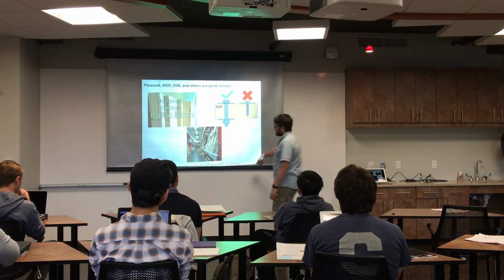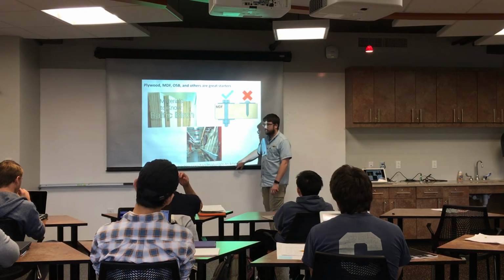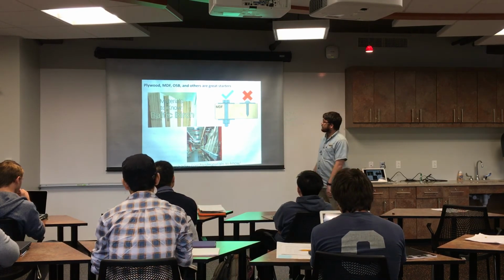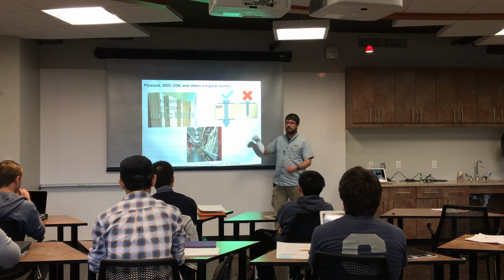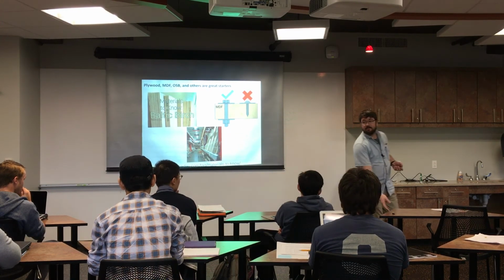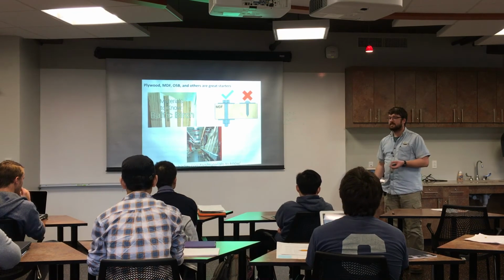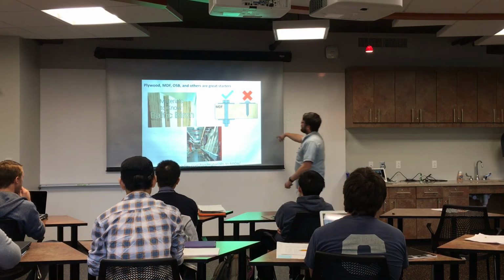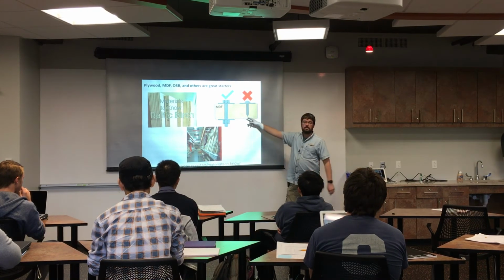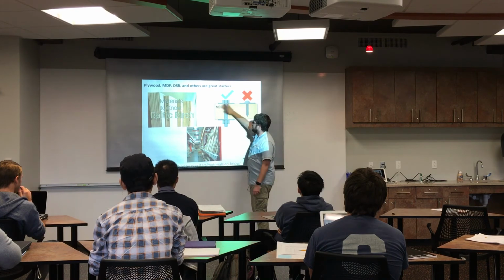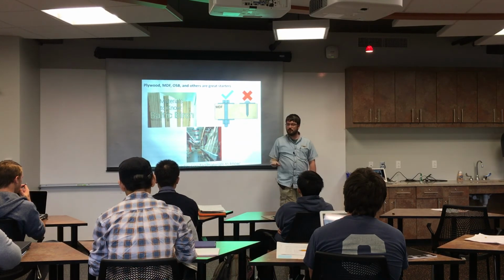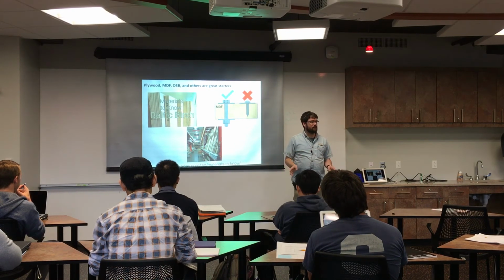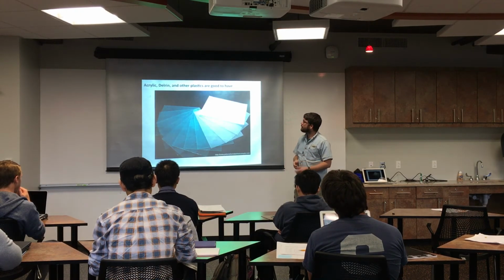There's this link in the slides, Hackaday, Materials to Know, that goes over a lot of materials like plywood, like MDF, and tells you things you should know. Like, for example, MDF, which is probably what these tables are made out of. Actually, it's what you get when you buy IKEA furniture, and it's glued together sawdust, basically. You don't want to just put a screw in it because those threads will not hold. It'll just pull out. So you want to go ahead and use a bolt, some nice big washers to distribute the load. There are all kinds of helpful tips like that on that website for all of these materials. So it's handy to go and look at.